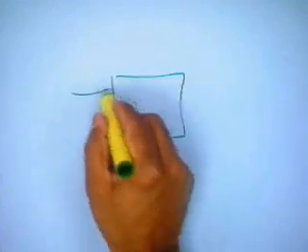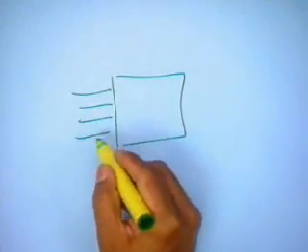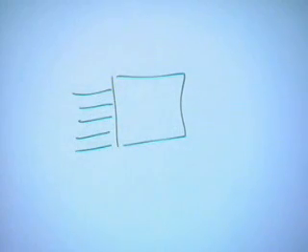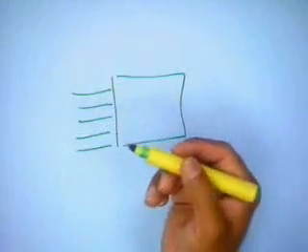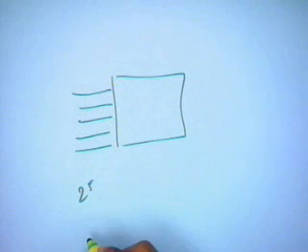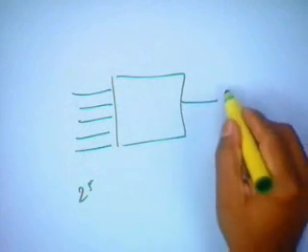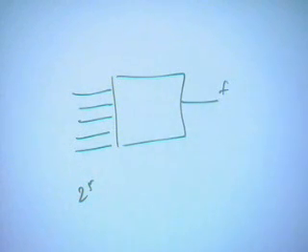For example, let us say we talk of testing of a combination circuit. We have a combination circuit, let us say it has 5 inputs. So, I apply all these 2 raised to power 5 possible input patterns, which is 32, and just count this particular function. I count the number of ones that it gets for each of the patterns. So, what you are essentially counting is the number of min terms that this function has.